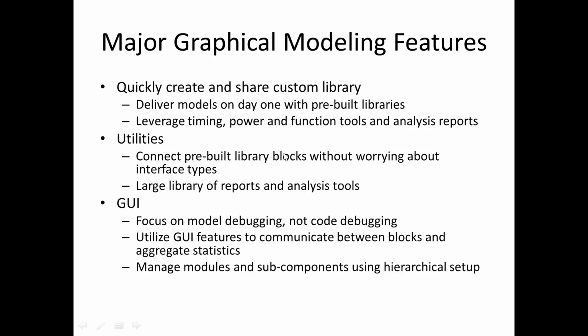Another aspect which I just showed you is all these different reports and analysis tools that are already pre-available. The other aspect is the model debugging. You're not debugging code in this case. You're really debugging how your system is operating, how your system is behaving. So you can use a lot of the GUI features to communicate between blocks within the model and also aggregate statistics all in a remote location, so you don't need to have it all tied into the blocks themselves.